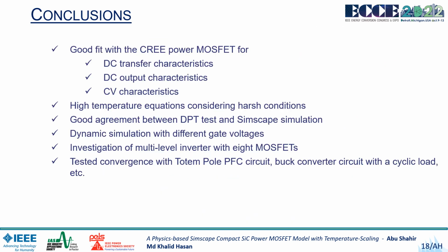The experimental results using the Cree power MOSFET have shown that the model produces a good fit for the DC transfer characteristics, DC output characteristics, as well as for the CV characteristics. The high temperature equations are added to simulate the model in harsh conditions. The threshold voltage is reduced at high temperature and the drain source current increased as expected.